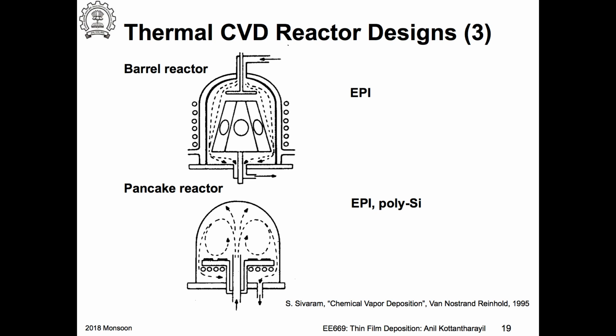So that is the first one, from the flowing gas. The second was, through the already grown oxide layer, there is diffusion, right? And then the third one, there is a reaction at the interface, meaning at the surface of the silicon. Okay, so three fluxes. And when we did the analysis of the oxide growth, the Deal-Grove model, when we developed it,